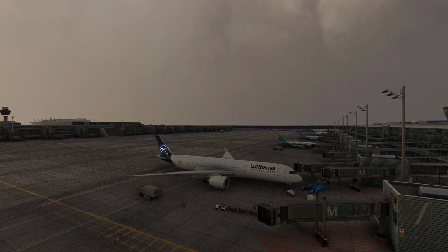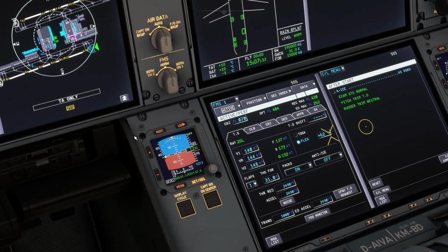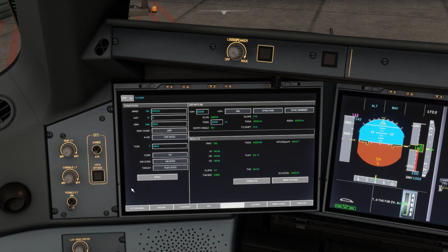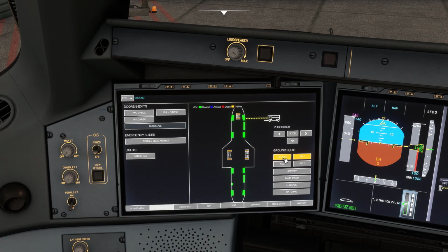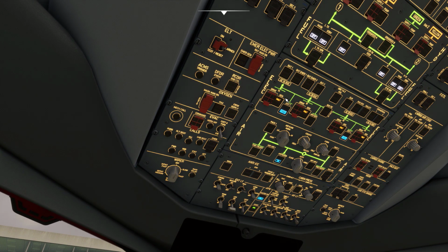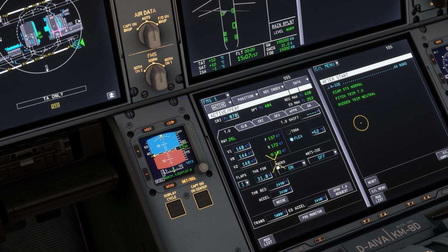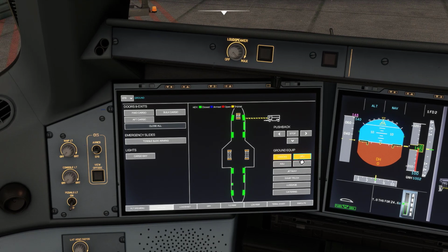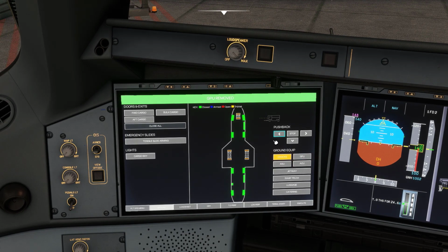Well, now let's taxi. So we have a pushback clearance and clearance to start the engines. We are just doing that now. So ground. First of all, remove the GPU because we have the APU running and the bleed is on. It's not on. Let's put everything on here as required. So the air conditioning would be working, but will soon stop working because we are starting the engine. GPU can be removed. The chocks, we have the parking brake set, can be removed.